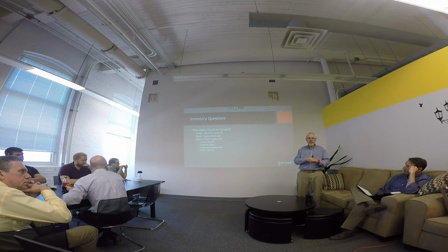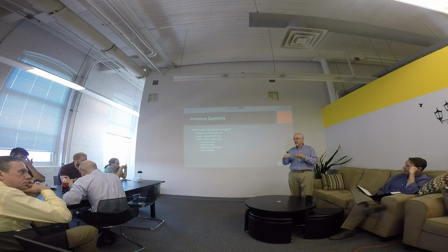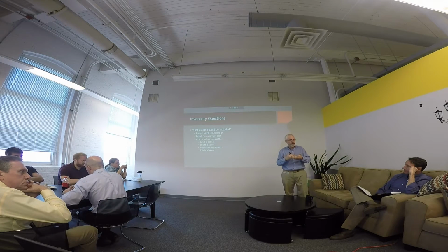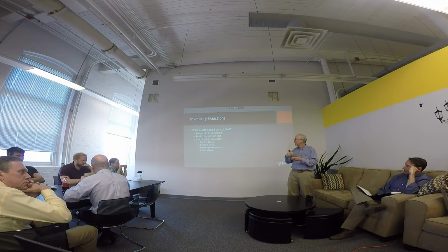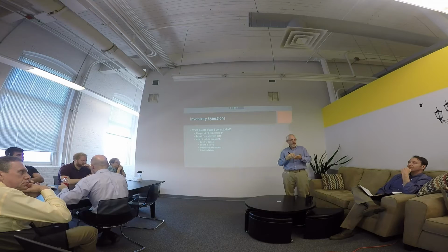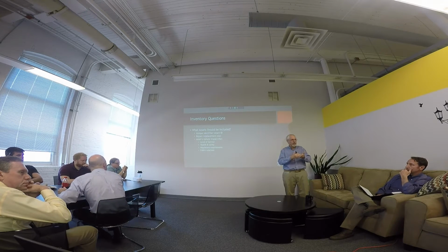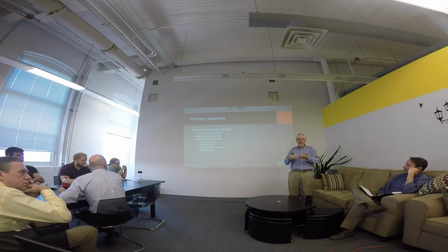For storm drains, it may be linked to where the outfall is. So if you have a manhole number or a catch basin number, it may have in the identification a unique number for where the outfall is. These are some of the things you need to think about in setting up a unique identifier for the different types of assets. It also may have the type of asset in it, like manholes will have MH for a manhole.